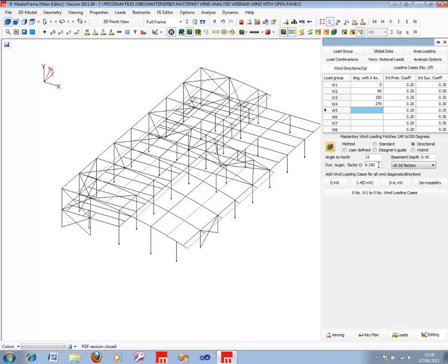So a quick look up in a table in the code might even yield that the number can come down to 0.05. So immediately we've taken 20% off the value of wind there. So that's quite important to pay attention to, and arrive at a suitable value.